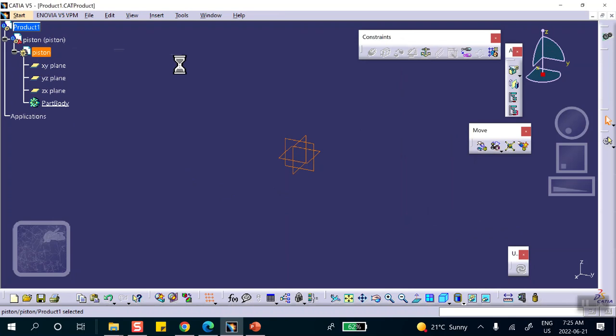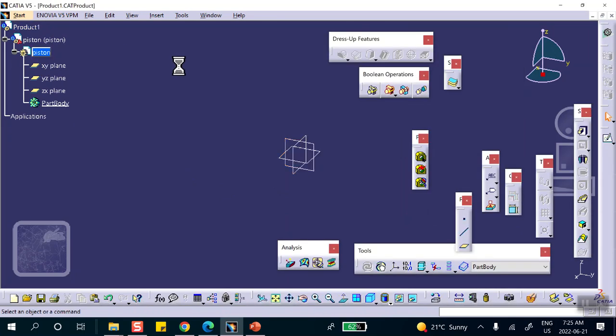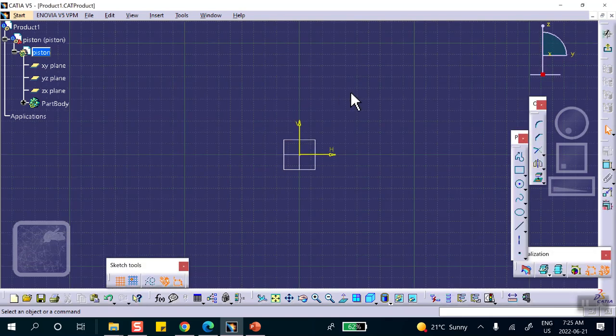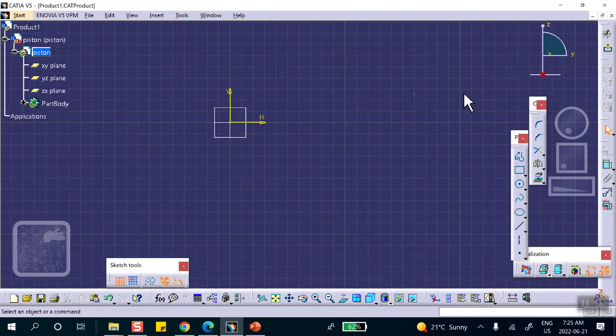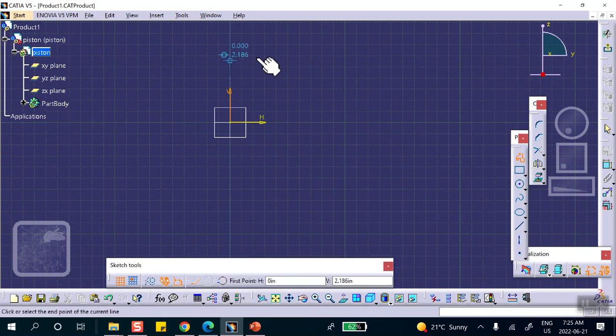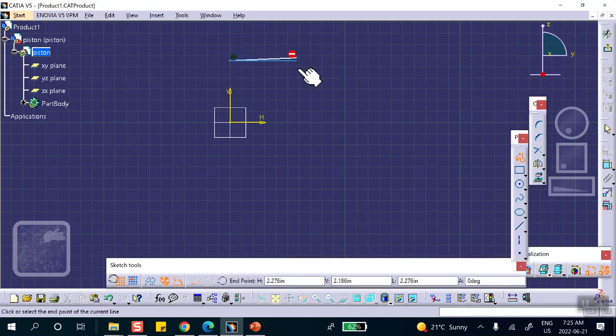Double click on the piston, and I'm going to make it. So on a convenient plane, on that vertical plane, I will sketch something that I will shaft in just a minute to get the piston. So let's go ahead and do this. We're going to draw something like that. This is going to be the cross section of the piston. It's okay. We'll clean it up. This is the piston ring. I'm going to make just one of them, not two, not more than one. Go down. This is going to be the cross section of my piston, and like so.